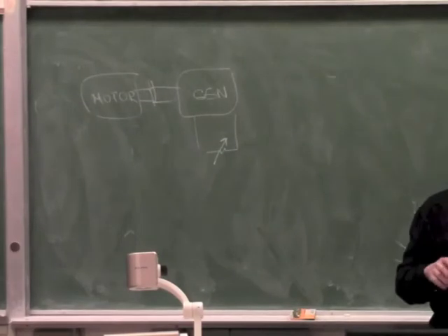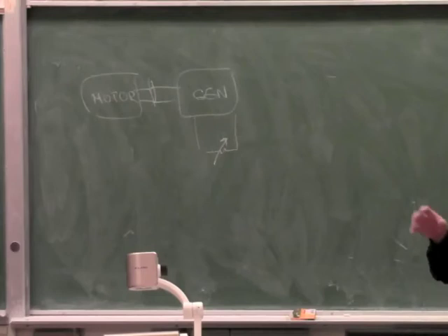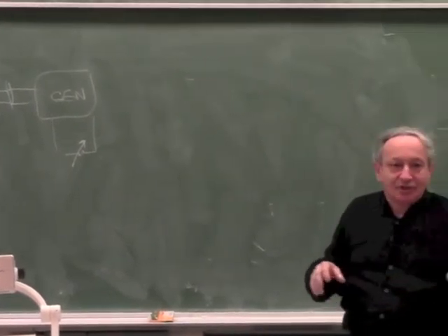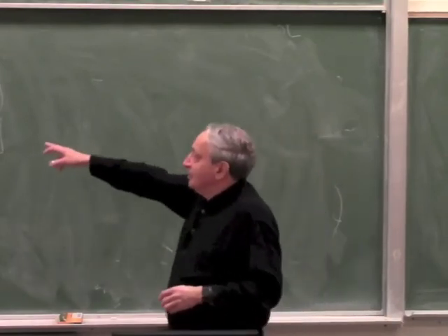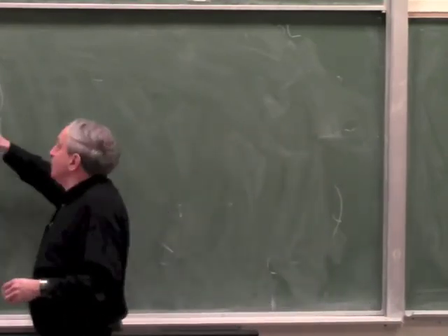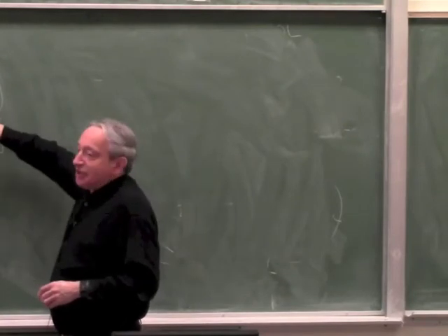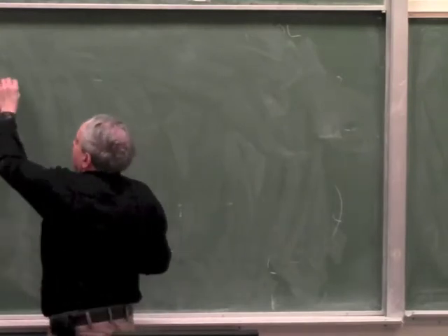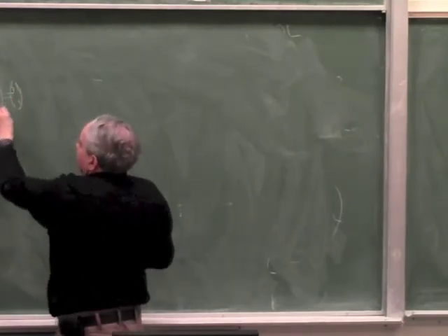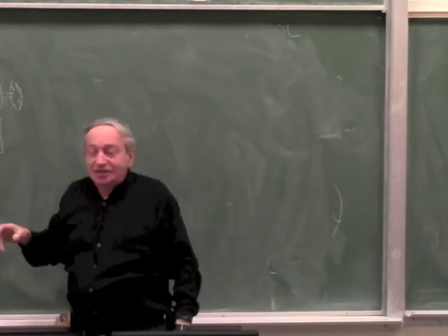And when you go and get your car tested for emission, once in a few years you have to take your car to the testing station, and they put the car on rollers and run at different speeds. That's what they do. This is your car, it's driving a generator or they change the load. And here you can measure the speed of the generator by the voltage or by the RPM. Let's say it has an encoder. It's very easy to measure the speed, it's easy to measure the torque, okay? And that's called a dynamometer.